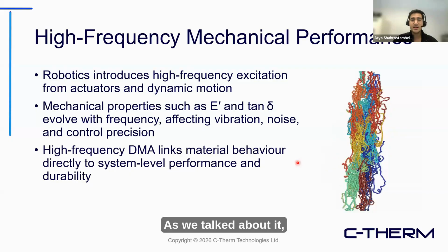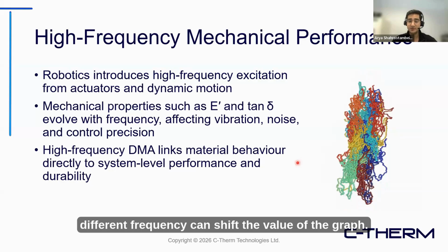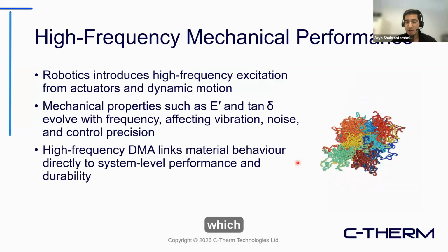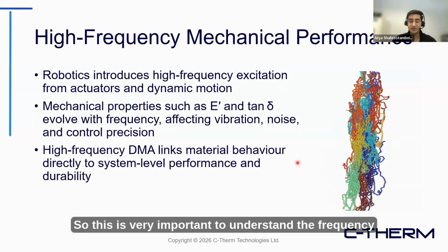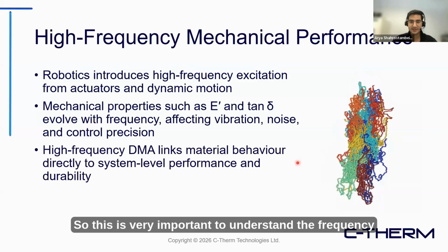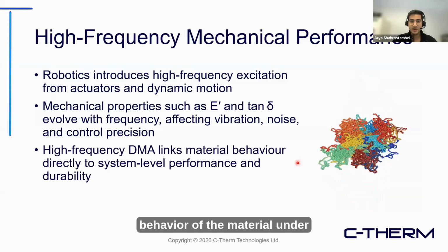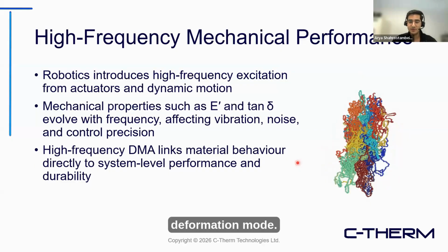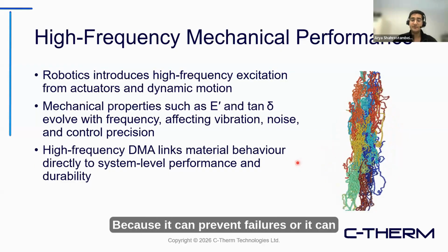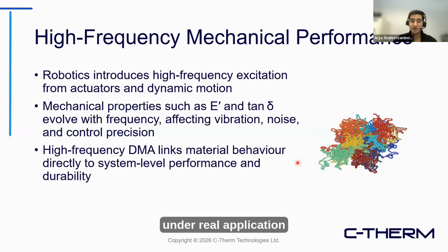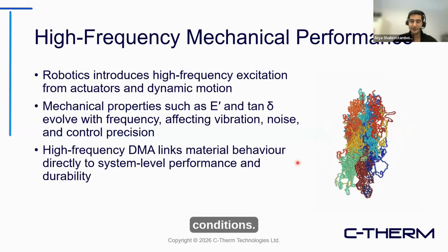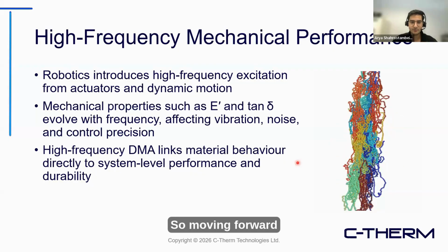As we talked about, different frequencies can shift the value of the glass transition temperature, which can affect the performance of the material. So it is very important to understand the frequency behavior of the material under deformation, because it can prevent failures or significantly boost the performance of the material under real world application conditions. So moving forward